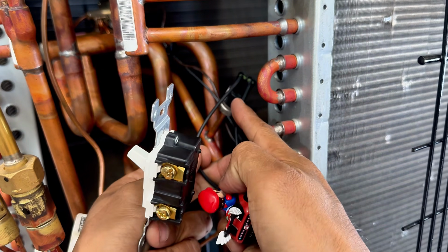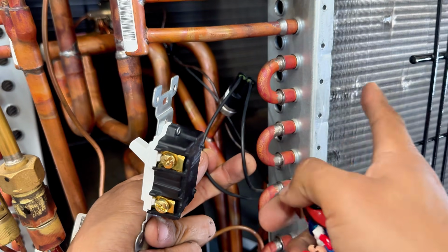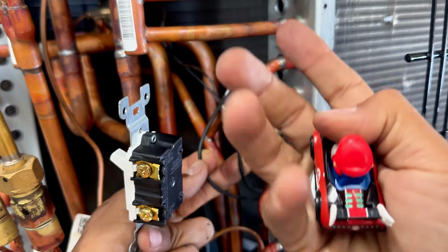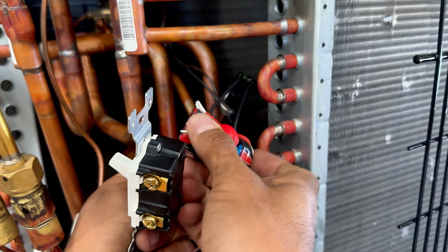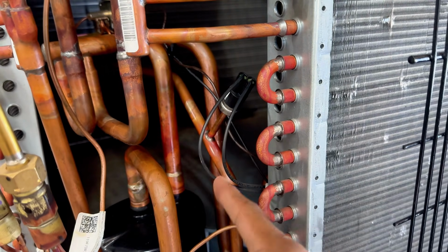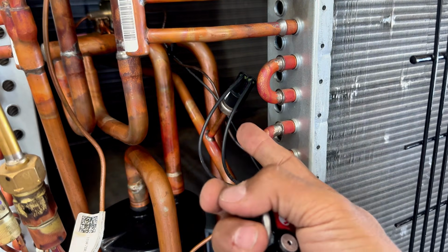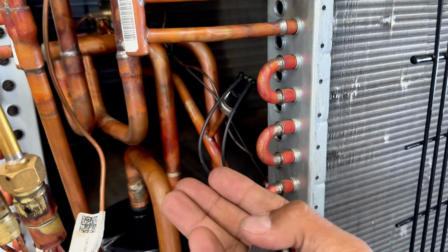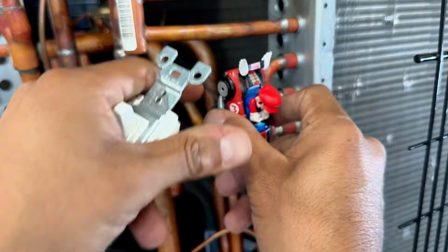That bridge only stays open if, remember we talked about it, the high pressure switch. If the condenser is dirty, the condenser fan turns off, pressure goes up, and it opens. But if there's no issue, great. He goes through and he comes down this way. So Mario can continue going through the route. And this is doing its job. If it goes off on high pressure, it's because you don't want to turn on the compressor. You've got to fix the issue as to why the pressure is going higher. But we're good. Let's say we're going through.